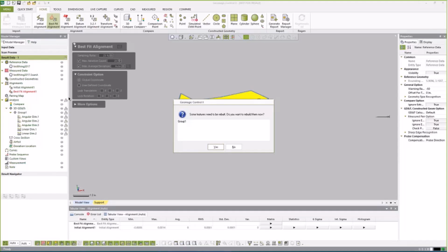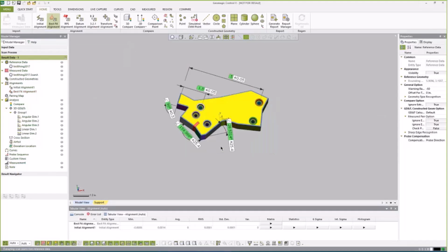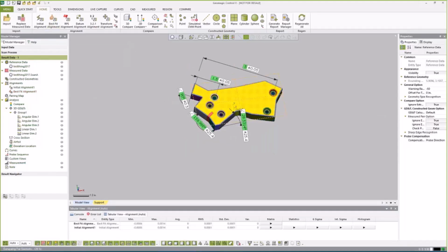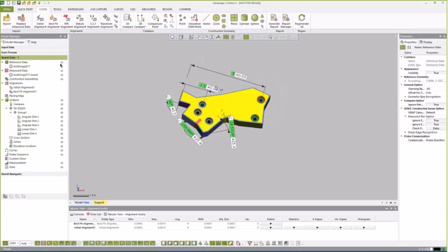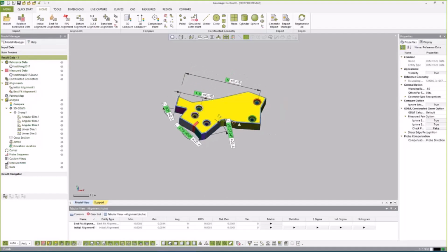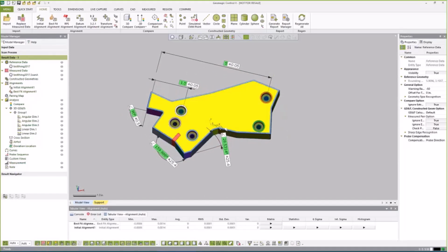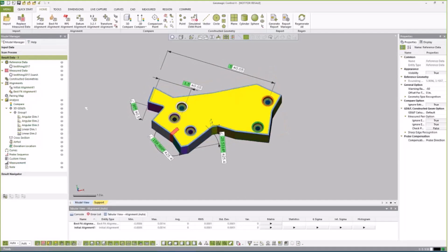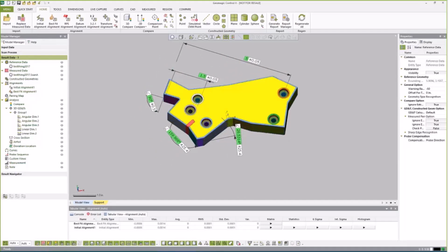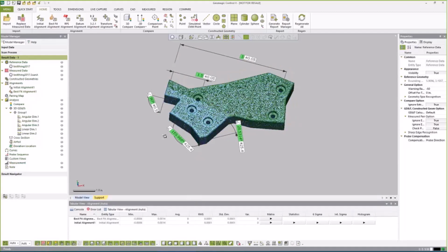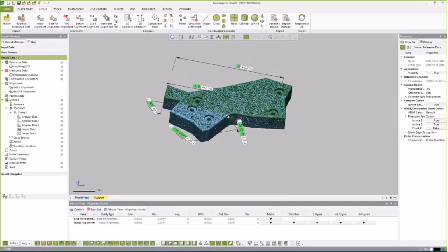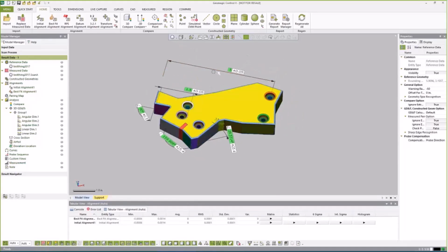So you can see right now it's all empty. It doesn't have measured data in it. Now it rebuilt it, and you can see that my tolerancing on my parts is really close, because there were two of the same essentially printed objects that I've scanned, so they're all really quite tight to each other. So the tolerancing is very, very tight to one another. We don't have gross manufacturing defects anywhere, but that's kind of a quick way to pull things out.